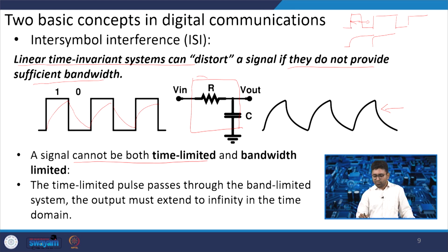What is happening is that one symbol is interfering with another symbol. So, instead of 0 you will find a certain amplitude. It will increase, then there is a little change, again it will increase, then decrease. The amplitude here, in reality, should be considered 0, but it is not 0, some voltage will be there.